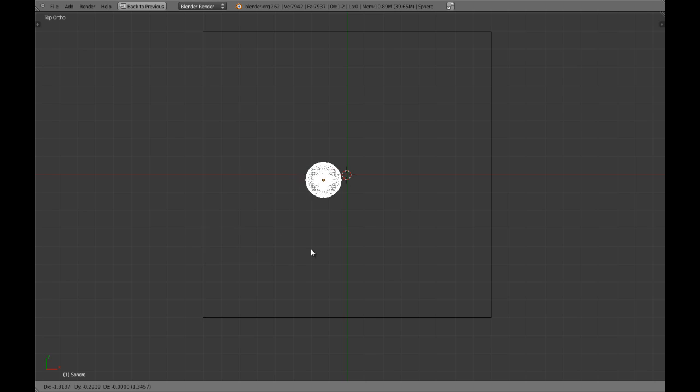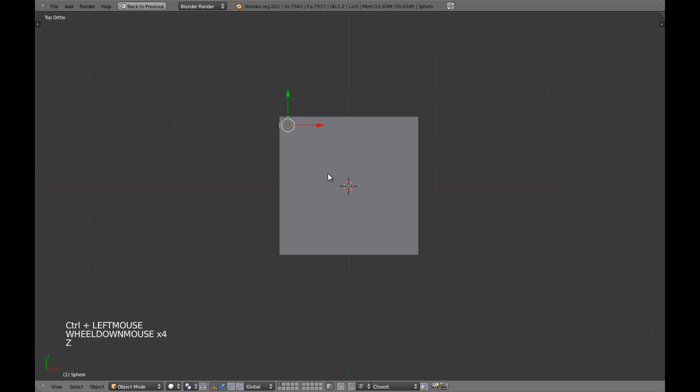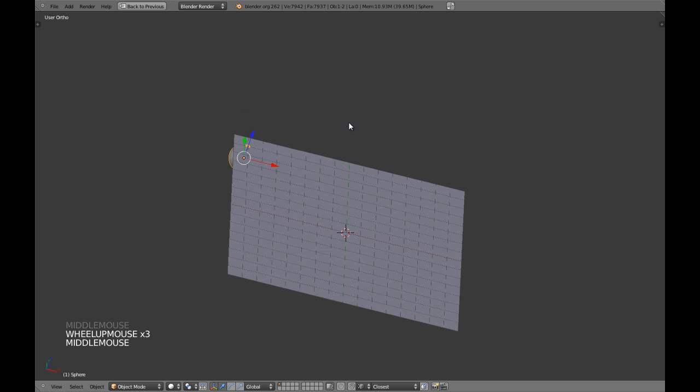All you have to do is press Ctrl during the movement and snap will be working. So for example, you will see that you get this circle when snap is activated. So if you see that my object or my faces or my vertex are jumping and this circle is in the view, that means that I'm using the snap. So that way you won't get lost if I'm using it or not. Okay.